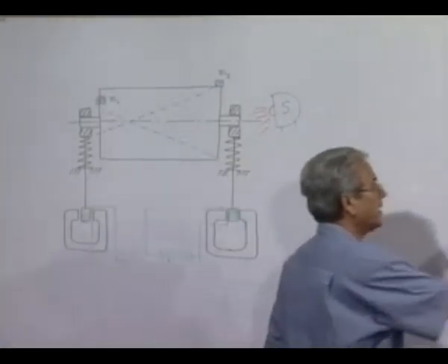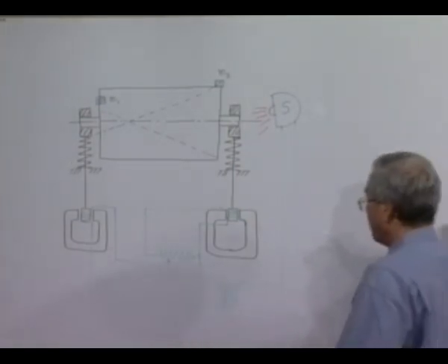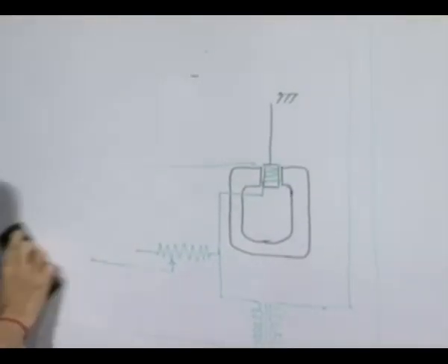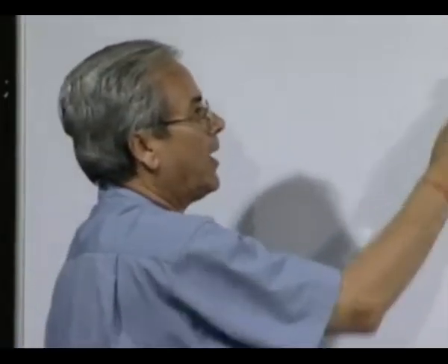Now, let us consider the case where the rotors are very large and you cannot bring them to your lab to put on balancing machines, like a turbine rotor or a huge industrial fan. Such cases have to be tackled and balanced in their original position, or in the field itself. That is why this technique, which I will now present, is called field balancing. It is very important, particularly for engineers who are working in the industry.